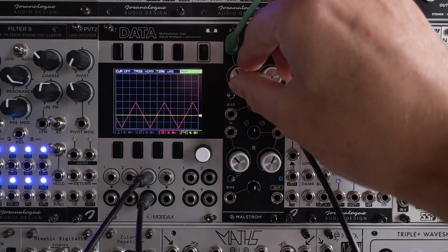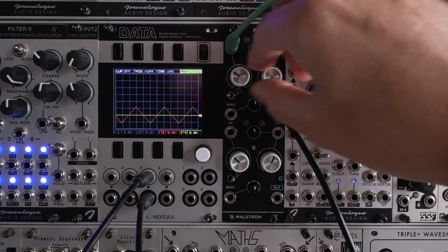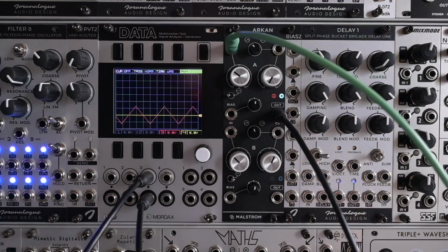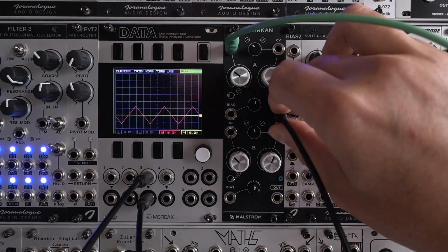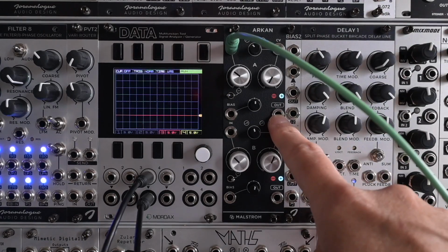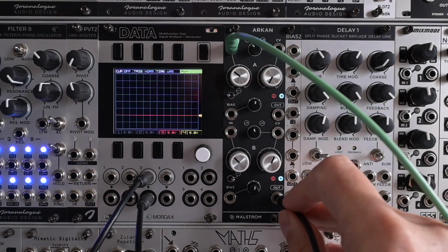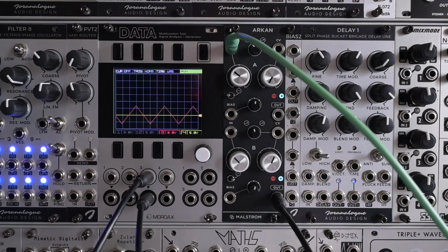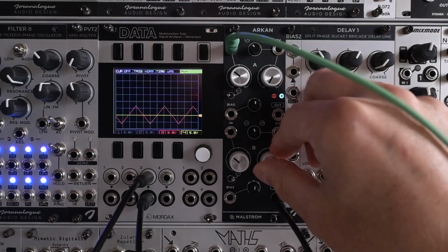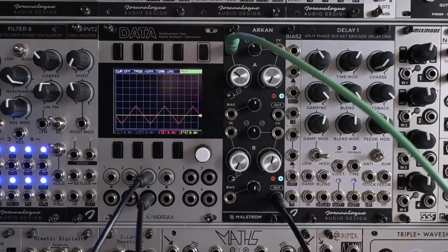And as I showed you before, you can amplify it or attenuate it. You can control the output volume with this knob. Now, when nothing is connected to this output, the signal we're sending on the top here will be present at the bottom output as well. And it doesn't matter what the settings on the bottom channel are. The output of this one just gets mixed with that one.